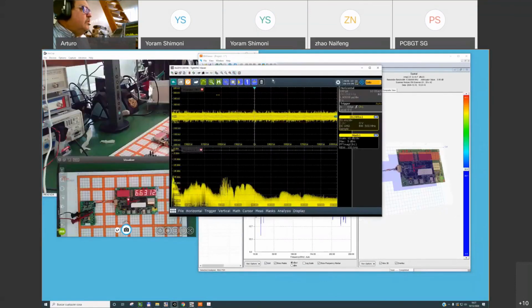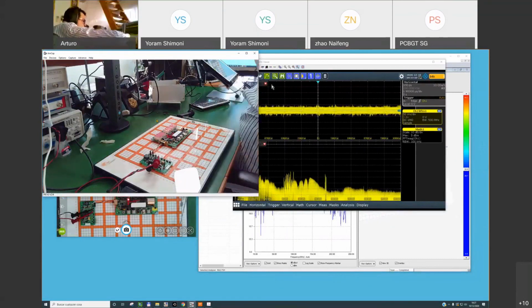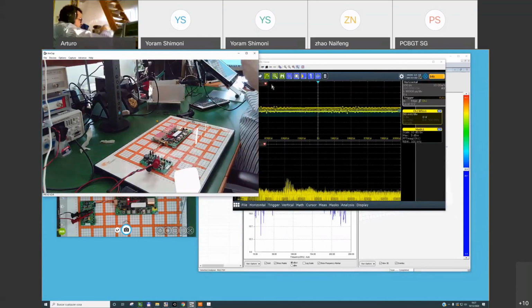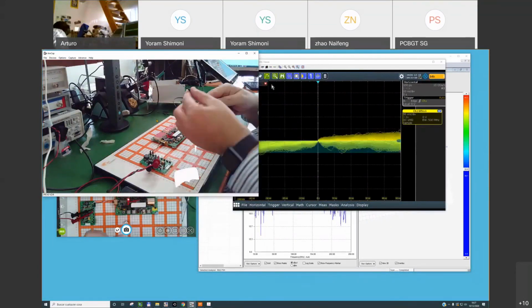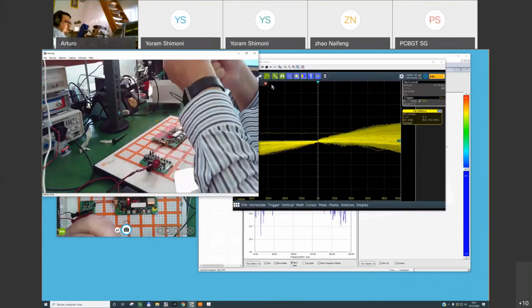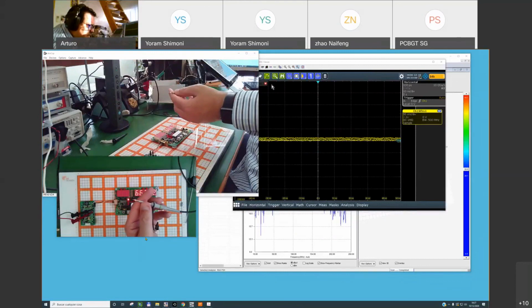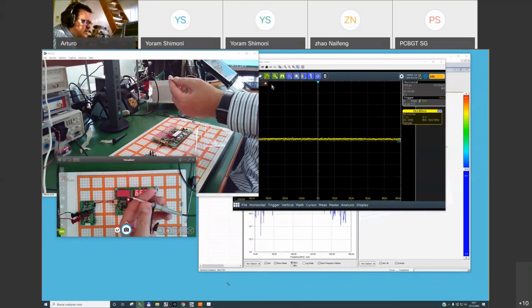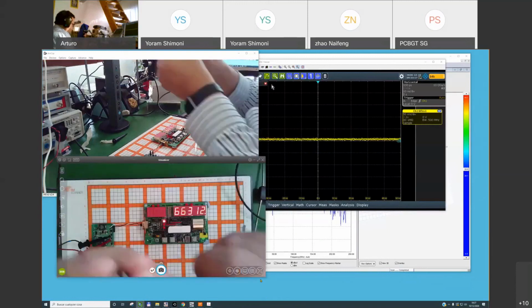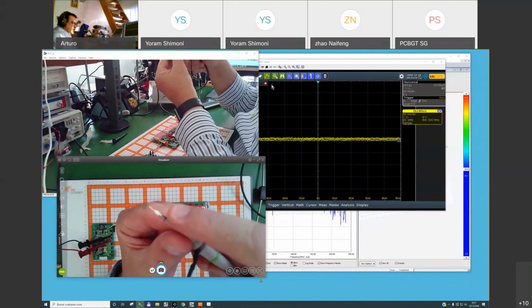Okay, if we go to the oscilloscope, I can use a passive probe to connect to channel number 1, press it, and then when you are interested in looking at the switching activity of any power electronic circuit, remember that you need to remove the cap of the probe, and then we need to prepare some kind of accessory to avoid pigtails while measuring.